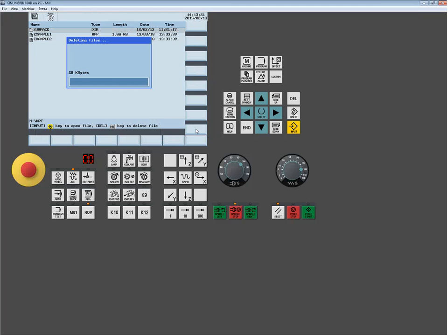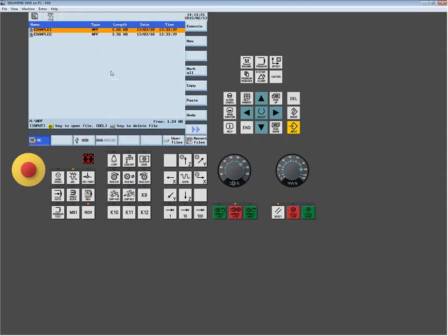Then from there, anything below these semicolons, so all the semicolons are what we call comments. So anytime you want to put any type of user note in the program, just simply put a semicolon. Everything after it will be ignored. Then I start to see the header protocol, my tools, my tool changes, some technology statements, and we can start moving down from there. I see my spindle commands, different offsets, different things being fired here.